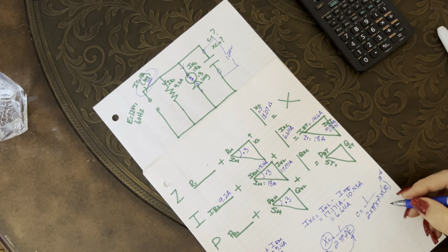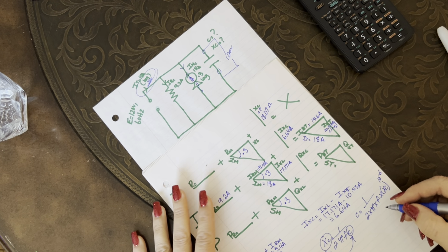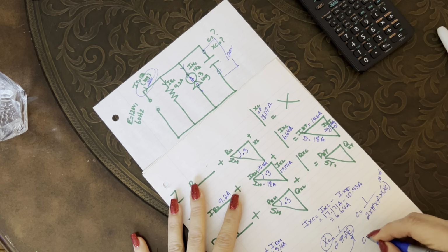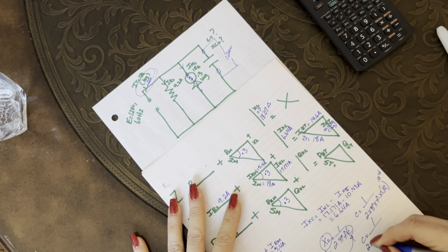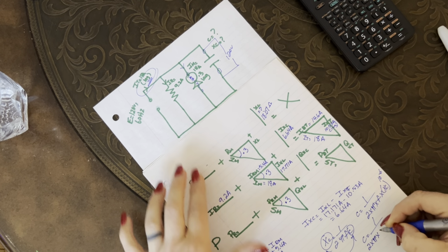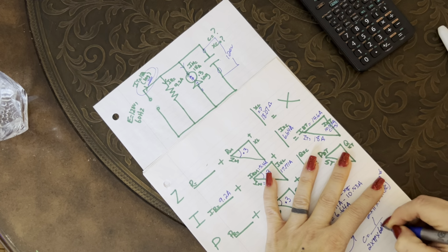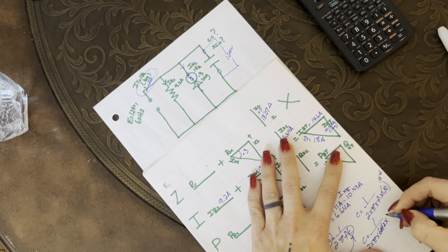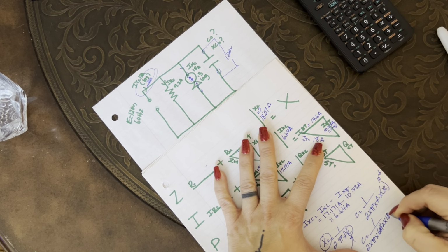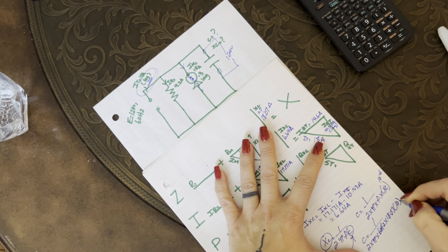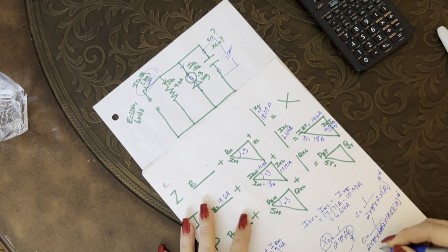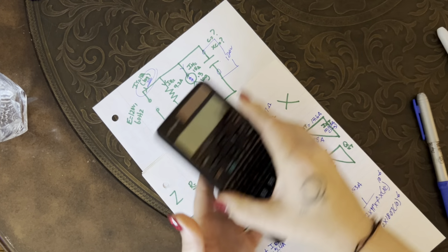Capacitors are always rated in microfarads. So that would be punched into your calculator like this. So 2 times pi, frequency is 60 hertz, times my capacitive reactance, which is 18.07, and we're applying the 10 to the negative 6, and then we're inversing that value to find our capacitance, right?